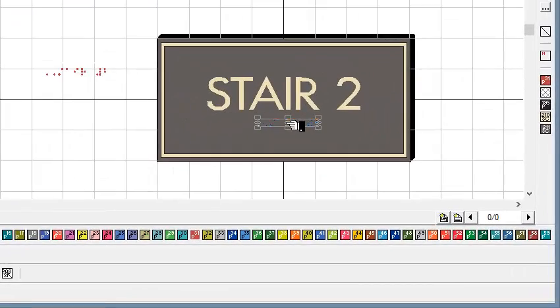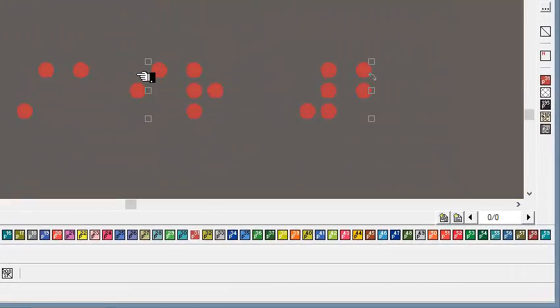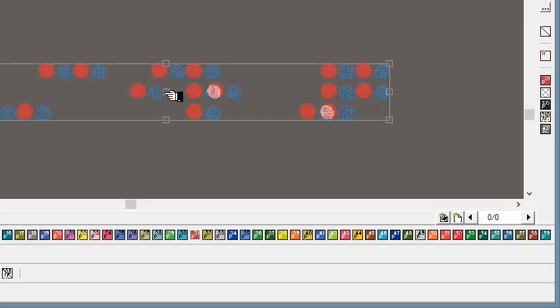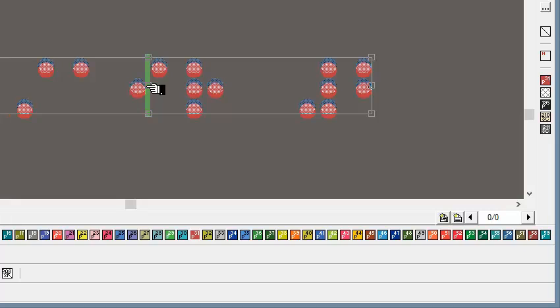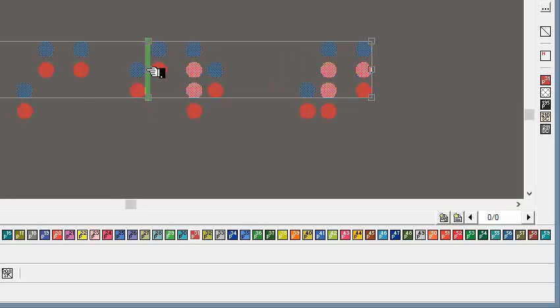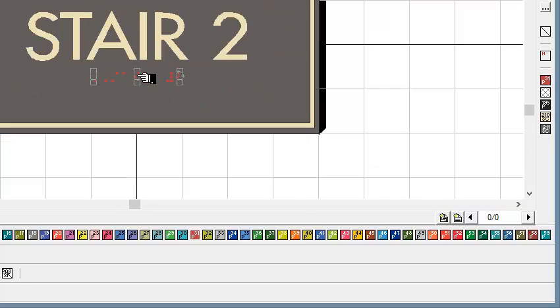And then we're going to place it so that it snaps to our center there. You can see that pink line right there snaps it. Then we want to make sure that we are at least 3/8 of an inch below that other piece. So we'll let that go. An easy way to do this is to take a measurement from there. We're going to take a look here, and we're just going to put it there, and we'll be plenty fine.